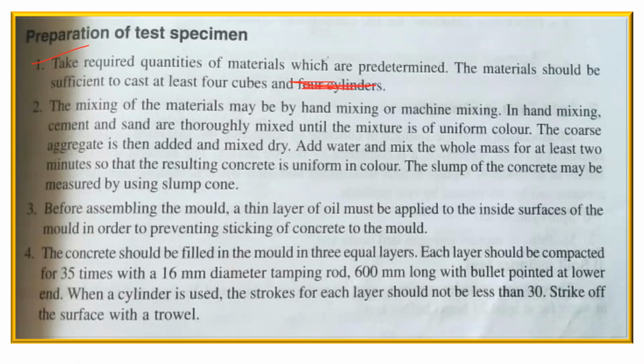What do you mean by this? First, we have to decide what grade of concrete you're going to prepare. Let us say I'm preparing an M25 grade. Now, why this M25 only? Why am I not taking M20? We'll come to that a bit later once we finish this. There's a big theory behind that, right? So this is done. Based on that, you identify how much cement, how much coarse aggregate, and how much fine aggregate is required. With the help of that, you prepare a concrete and you cast the cube.